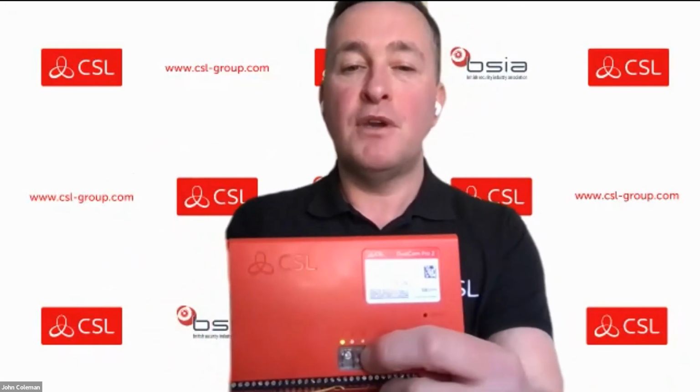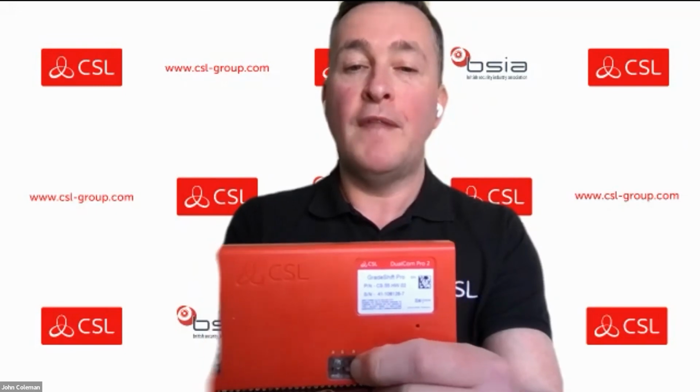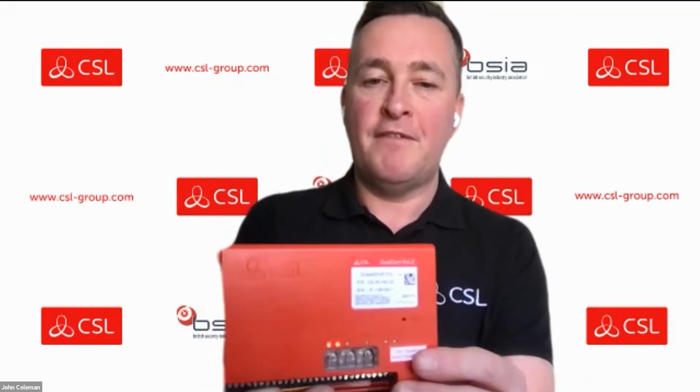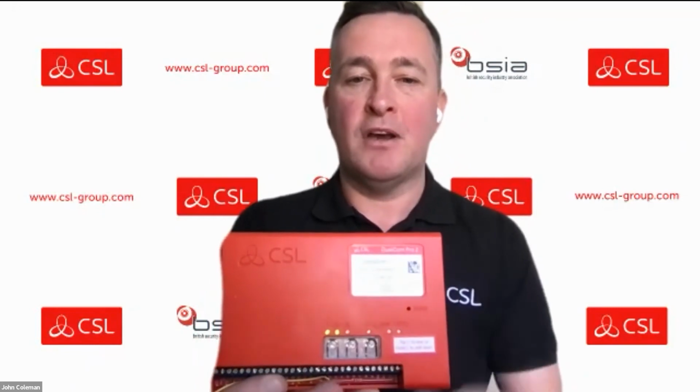If I want to fail the primary path, then quite simply press and hold button B for a couple of seconds, and I will see that that has now gone into path fail as well. Again, check with the monitoring station that they've received those path fails. To restore the path fail, quite simply, press button A, and it's now restored. Press button C, and it's now restored, and you've now got the devices back online.